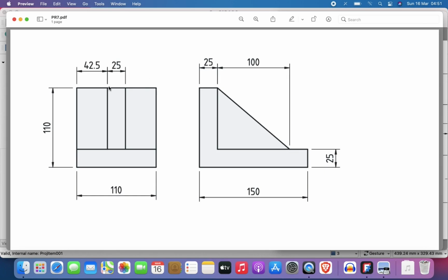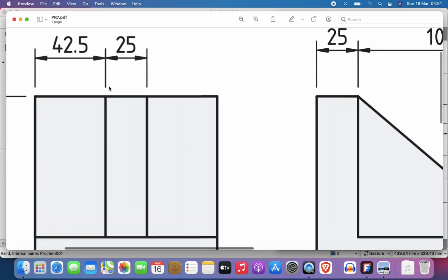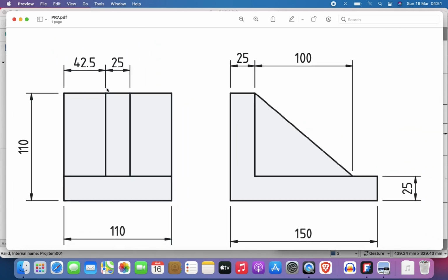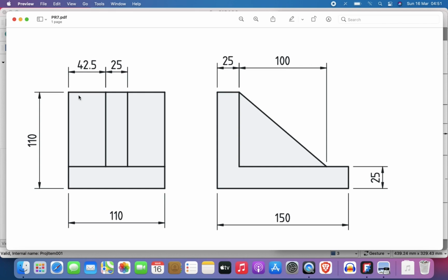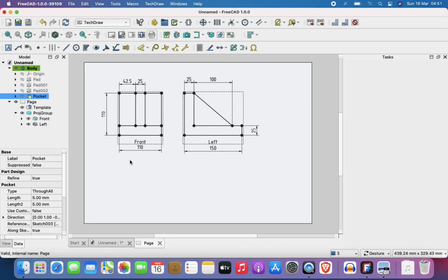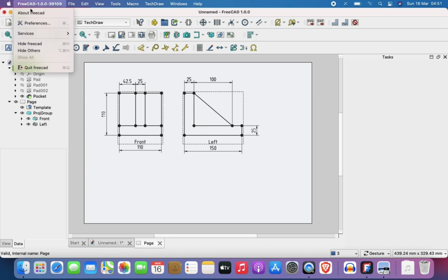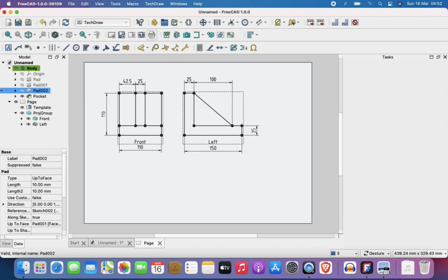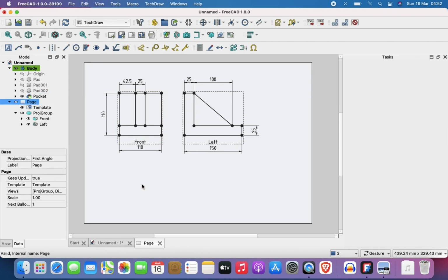So you would notice that here there is a little space between my drawing and the dimension that is created. For you, there may not be any space because maybe it's still working at the default. So now this is the way to change that. We go to preferences. Remember, we want to change 2 things now. We want to change firstly the color. We don't want it to be colored. And then secondly, we want there to be a space between the object and the dimension, which is the standard actually.